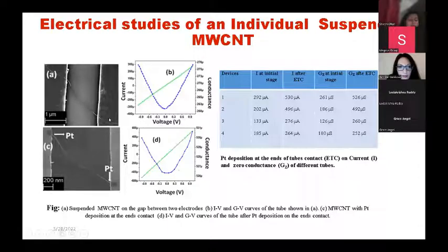on the gold pad. And these are the IV characteristics of these hanging individual CNTs. That is a 3 micrometer channel length, and this is a gold pad. After that, we noticed that when we deposit any metal, here I am using platinum, in a GIS system, that is the EBID technique. Sometimes we call it the gas injection system, sometimes it is called electron beam induced deposition.